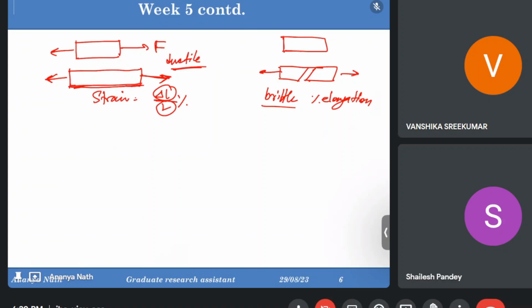Inside, there are multiple grains inside a particular material. These grains are not this much bigger; those are small microscopic grains. These grains will try to stretch themselves. Inside a particular grain, there are lattice structures. They cannot stretch beyond a particular percentage. So what happens is there will be mismatch, or there will be some dislocations, some newborn dislocations.